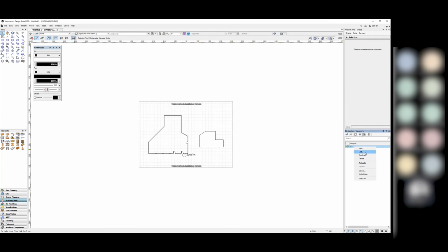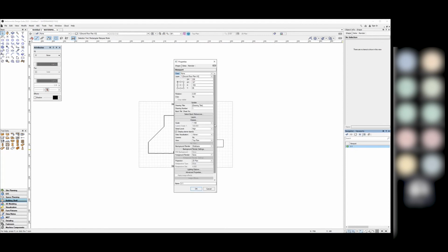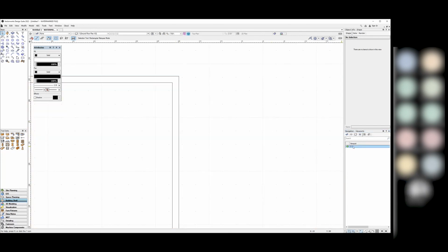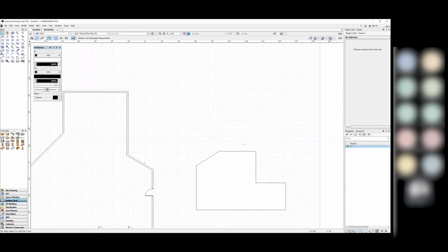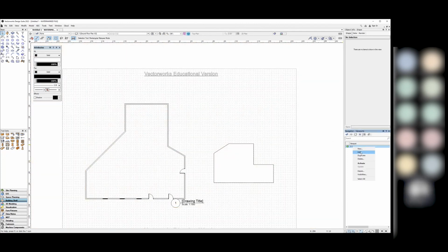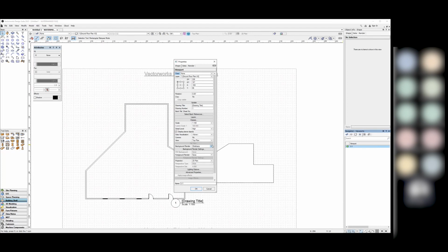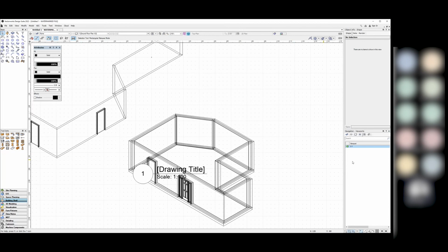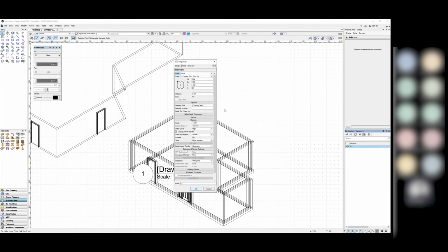Or if I wanted to change the visual style, I can edit that viewport. In fact, if I zoom into this, there's not actually any detail to that. Yeah, there's no detail to show off. It's the wrong building. If I were to change the view, if I don't want the top/plan view, if I want a right isometric, I can choose that. Currently it's on wireframe mode, so I'll probably want to change that to something like hidden line.